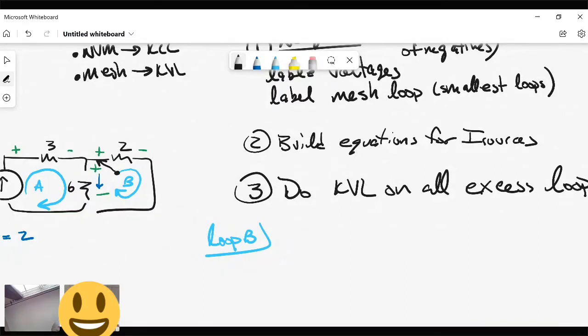All right. So I like to do it like this. When you go from plus to minus, we're looking at voltages. When you go from plus to minus, you're dropping the voltage. You go from high to low, you're falling. So it's going to be minus the voltage on 2 because I'm going from the plus to the minus. I know every professor does it a little bit differently. Some professors always do pluses. I like for it to make sense with respect to how I think it works. So I'm going down this voltage. There's nothing here. And then I'm going to go from my negative to my positive. You see that? So I went up in terms of voltage. From minus to plus is up.